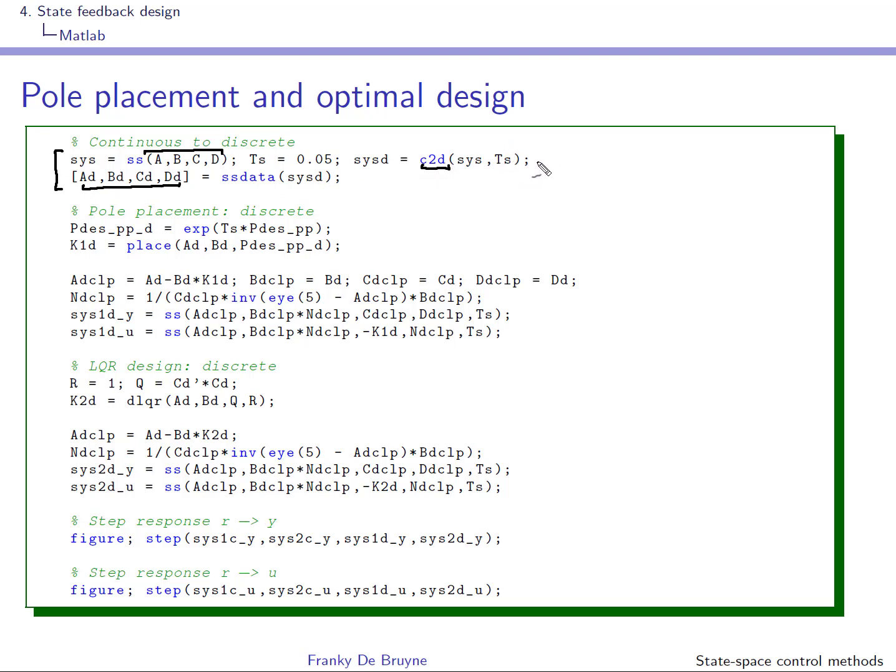If you're not using any argument, then you're using the ZOH method, and this is really important because you want to take into account the zero order hold. So please have a look at the help of C2D for more details. Here, as I've said, the continuous time poles are transformed in discrete time poles for the discrete time design, and this is simply done by the formula exponential of the continuous time poles times Ts.